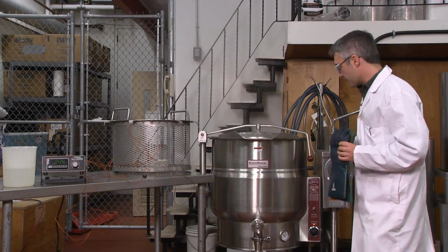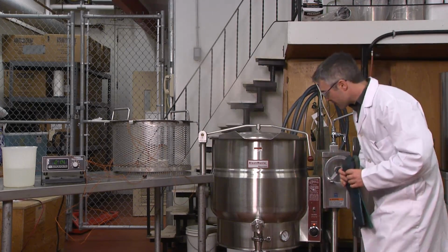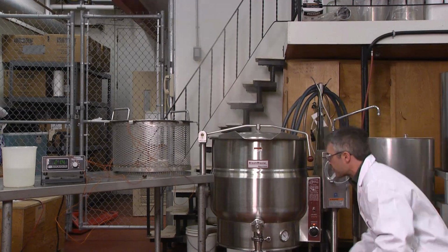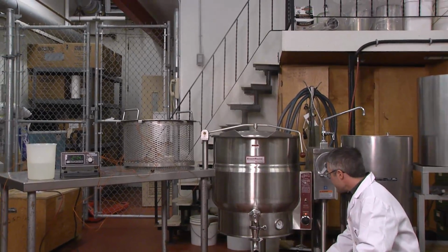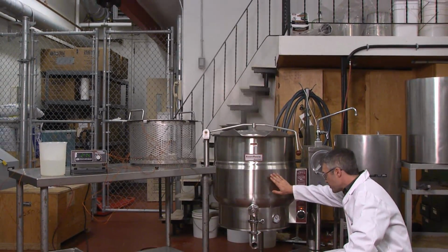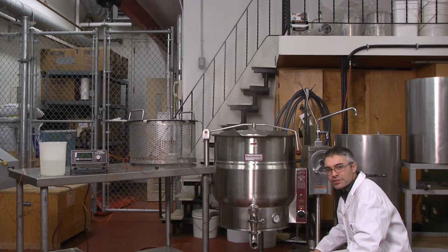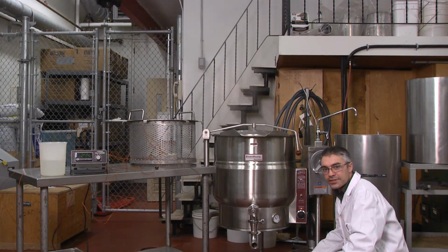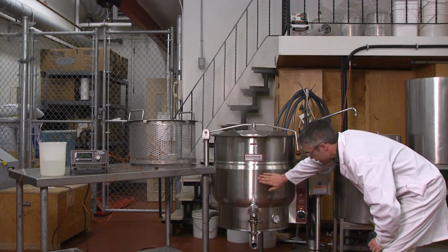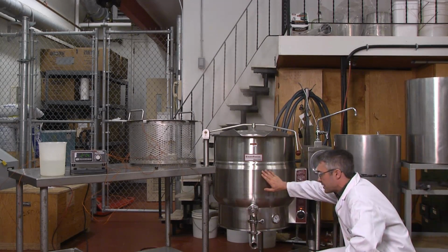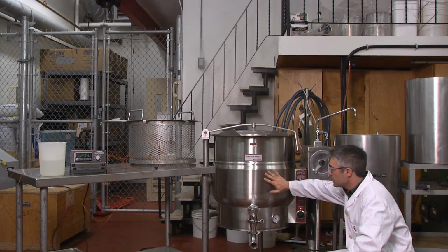All right, so what we have here is, as we discussed upstairs, our steam kettle. Currently we have it in operation, so the steam jacket, seen by the bulging area here, is now very, very hot. The steam within is currently at about 22 psi, and based upon your steam tables, you'll be able to determine what temperature, assuming we have saturated steam. When this cools down, incidentally, the steam will begin to collapse back into a liquid and will actually form a small vacuum within this steam jacket.